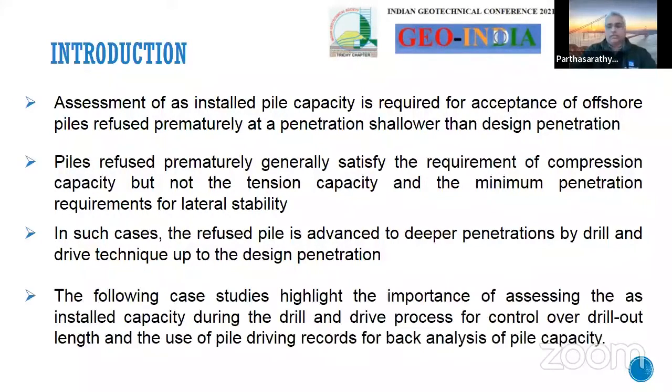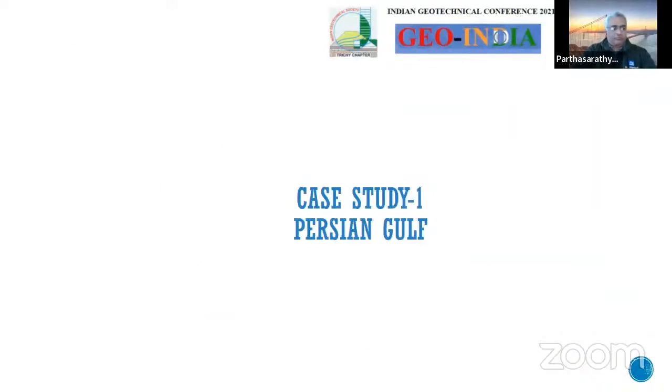And these two case studies illustrate the drill and drive technique. So the following case studies highlight the importance of assessing the as installed capacity during the drill and drive process, for control over the drill out length so as not to lose the skin friction, and the use of pile driving records for back analysis of pile capacity. I'll illustrate two simple case studies.